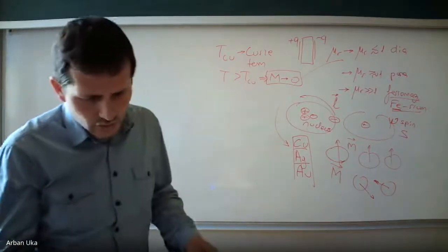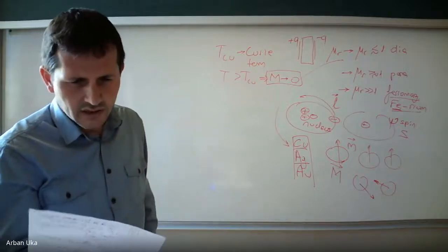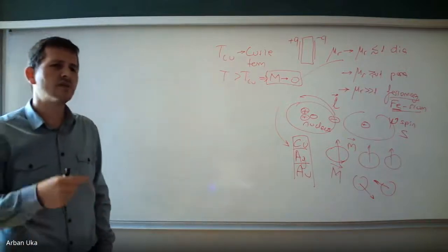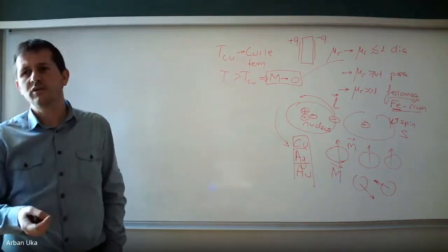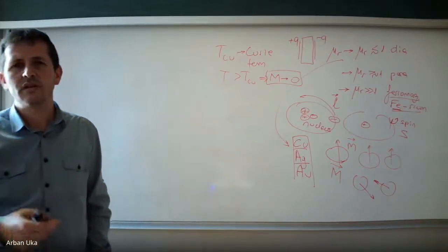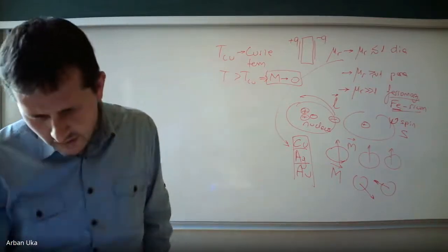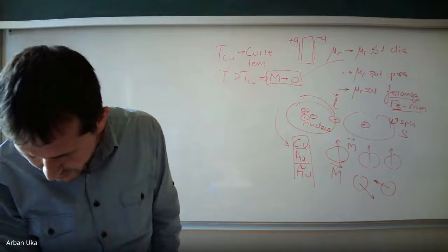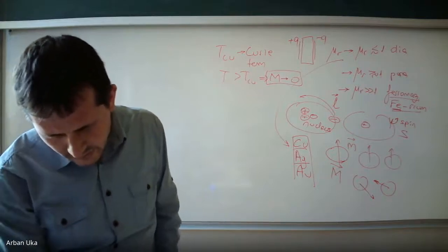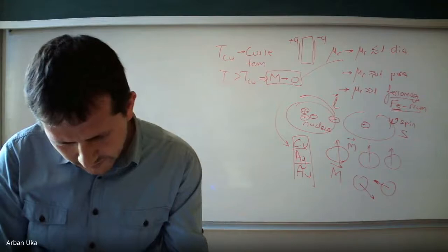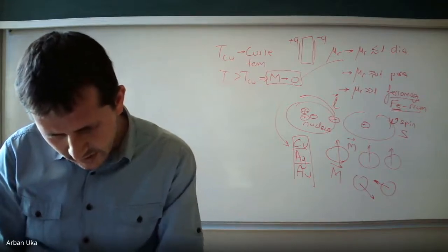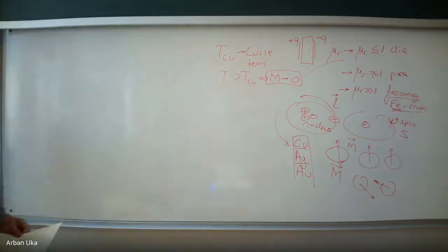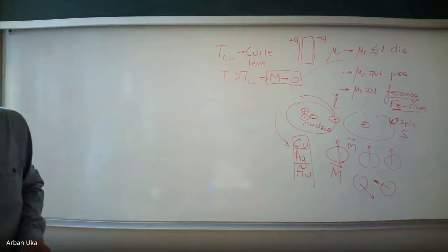So we should stay away from very high temperatures, and that's why in transformers, where we want a very effective transfer of the magnetic flux, we need to cool them down a lot, because once they get hot, things don't perform at the expected behavior that we'd like them to behave. Okay, so these were some elements regarding the behavior of the magnetic materials in general. Okay.